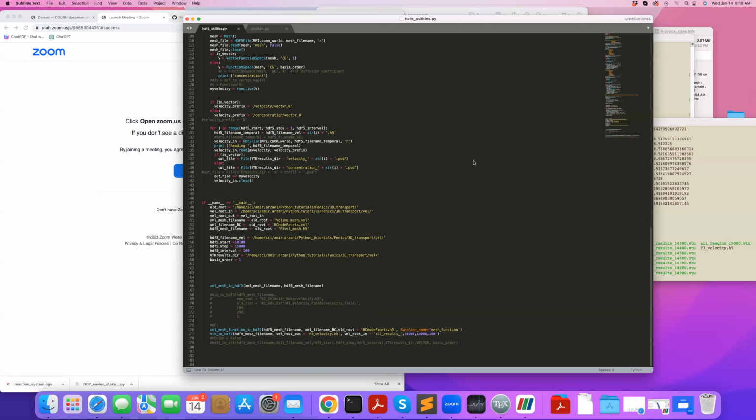Even if you're running an HPC code, essentially just one processor will read the file and things will still work. But the problem is, what if your mesh is huge, or what if you're constantly reading these input files? An example of that would be velocity for solving a transport problem. In that case, you want to make sure that you're saving your files and reading them in a format that supports HPC. The appropriate format for that is an H5 or HDF5 file, which I'll talk about today.